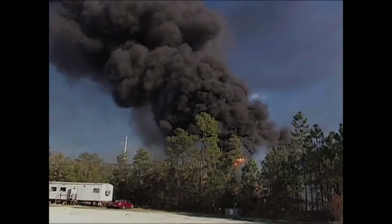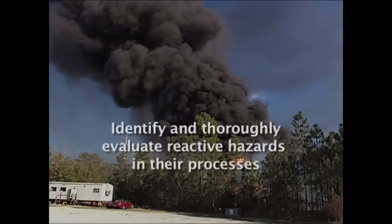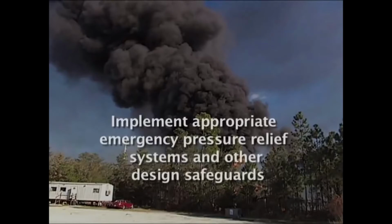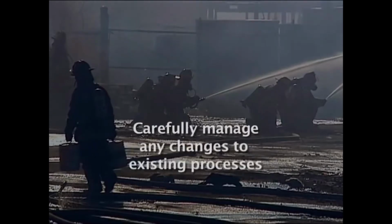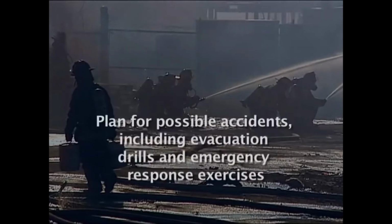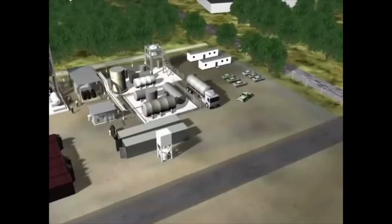The CSB has noted that to prevent reactive chemical accidents, companies should identify and thoroughly evaluate reactive hazards in their processes, implement appropriate emergency pressure relief systems and other design safeguards, develop effective operating procedures and training programs, and carefully manage any changes to existing processes, and plan for possible accidents, including evacuation drills and emergency response exercises.